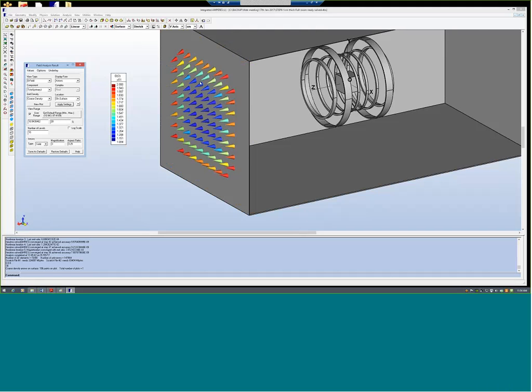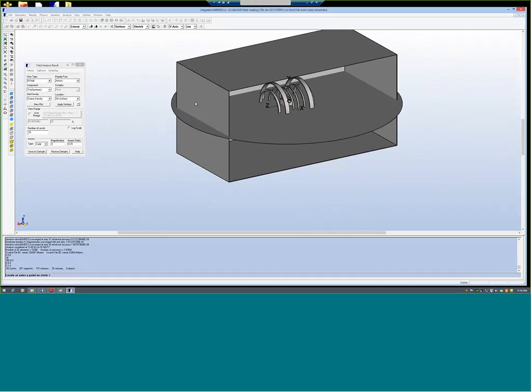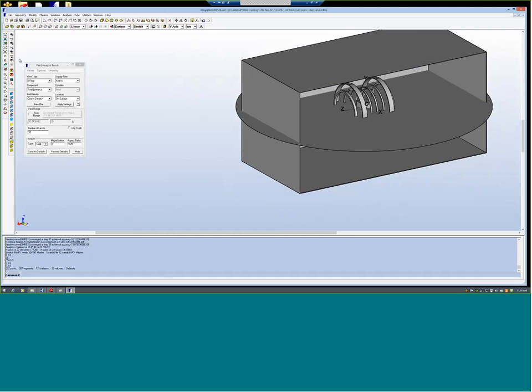So this is one thing. Now let's see along the axis what the fields are. Delete all plots. First we'll see around a big surface, which gives a better picture than only the axis. This time we will take a circle of 350 radius, centered at 0, 0, 0, with axis 0, 1, 0. Let's make it all on.